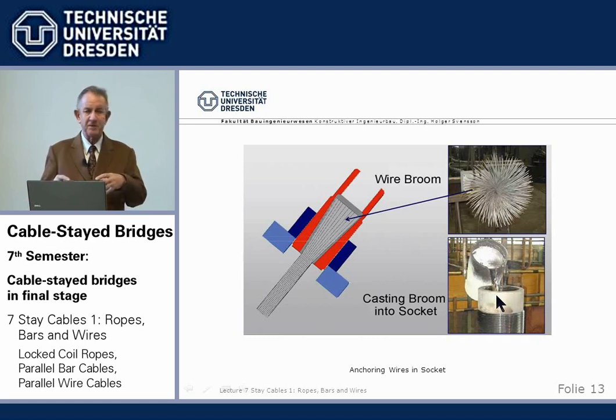Now this zamak is a long development. It's mainly something like 93% zinc, 6% copper, I think, and a little bit of other things. And the development went to reducing the casting temperature. Now, the zamak today has a casting temperature so that it is liquid of 425 degrees Celsius. In older times, the material had to be much hotter.